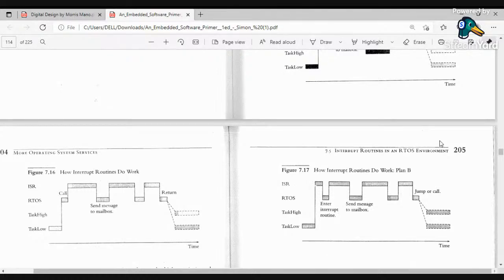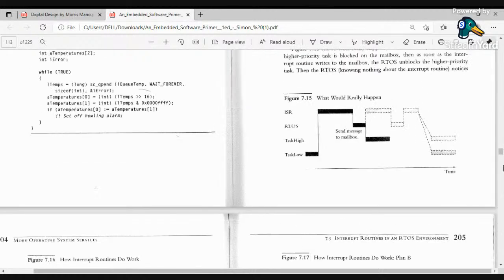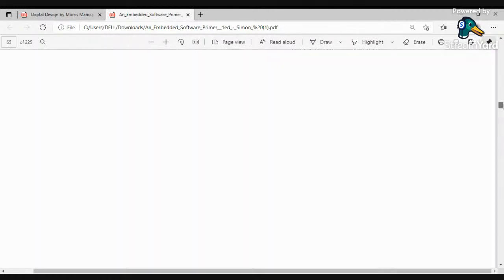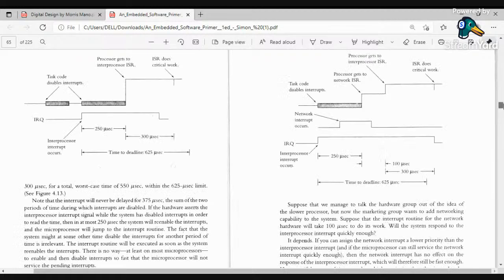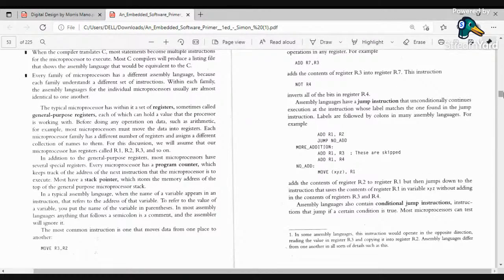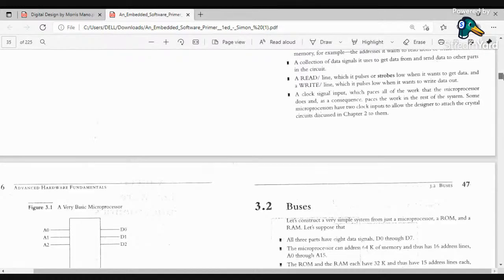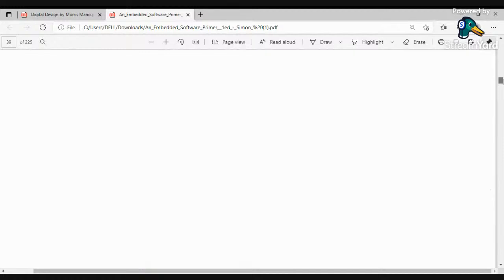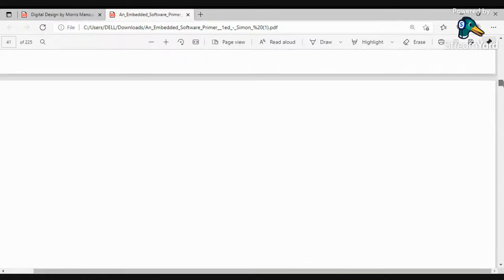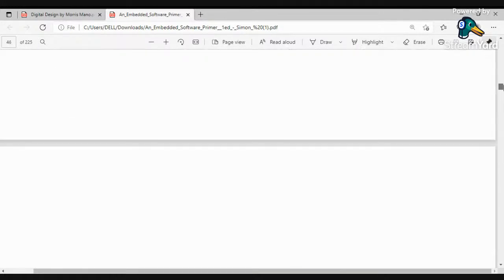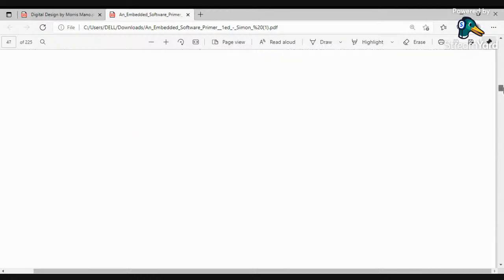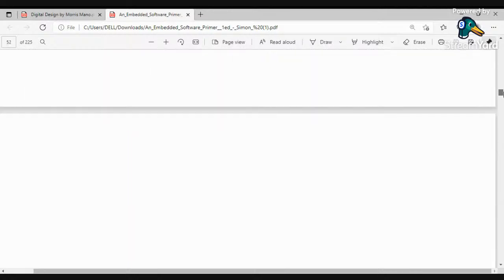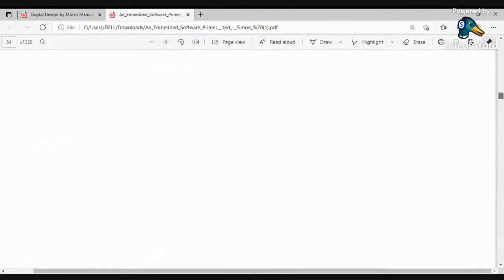And there are different ways that a solution is provided. One solution is they simply disable the interrupt between those two lines. We told you that, I'll go back to that. It clearly explains where the problem is in the shared data problem. There may be a chance of a shared data problem if the interrupt occurs between those two lines of code. And for example, if you enable and disable the interrupts between those two lines, so you don't allow any interrupt to occur between those two lines, you never have a shared data problem. That is one of the solutions that is provided, right?